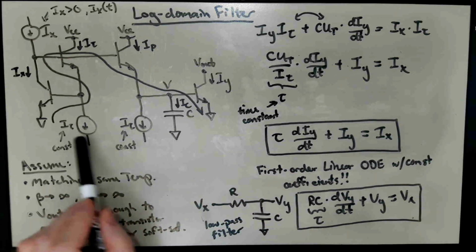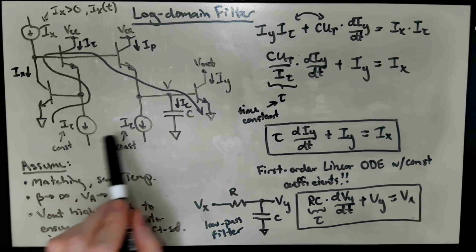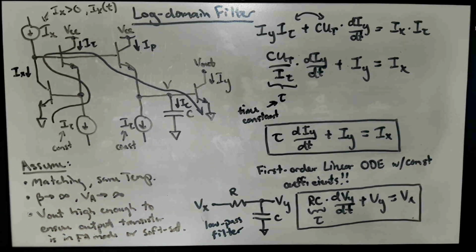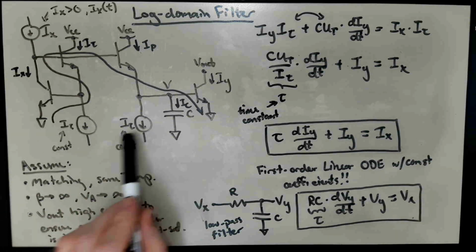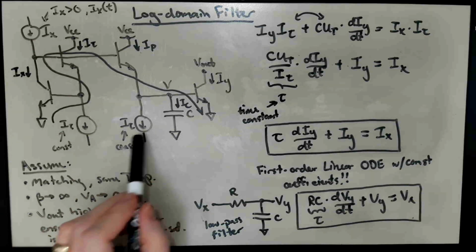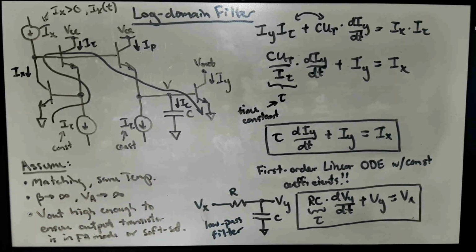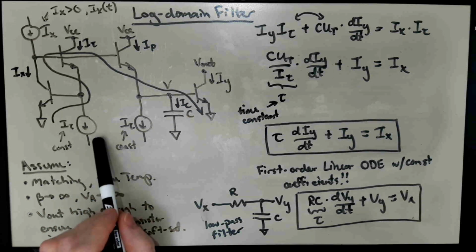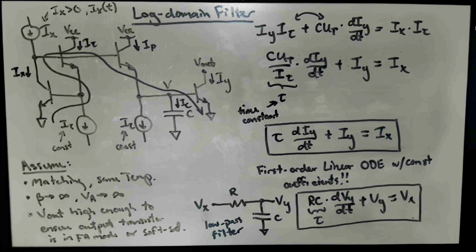What kind of range do I have available to me to tune these currents over, assuming, let's say, that they're made with NPN bipolar transistors? You've seen that now in Lab 3, that I can basically get currents that go from nanoamps up to milliamps, right?